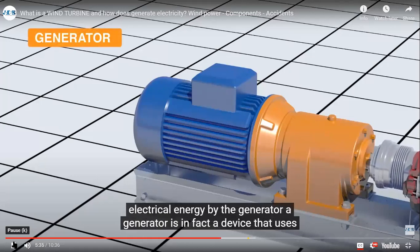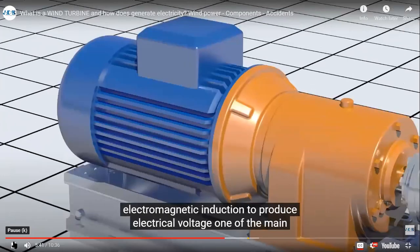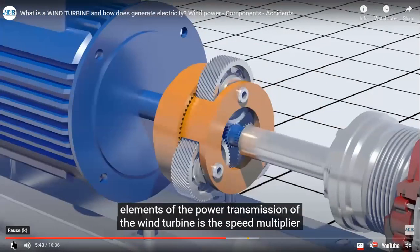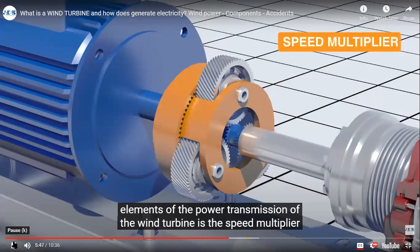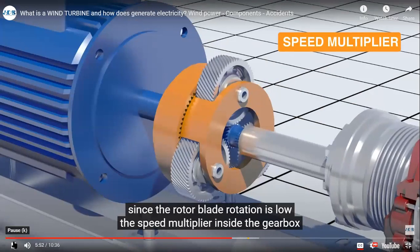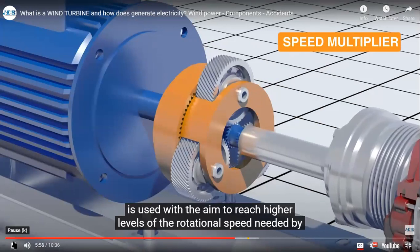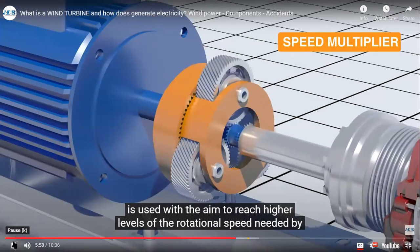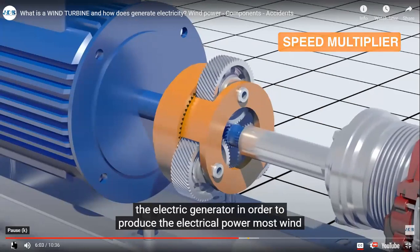A generator is in fact a device that uses electromagnetic induction to produce electrical voltage. One of the main elements of the power transmission of the wind turbine is the speed multiplier. Since the rotor blade rotation is low, the speed multiplier inside the gearbox is used with the aim to reach higher levels of the rotational speed needed by the electric generator in order to produce the electrical power.